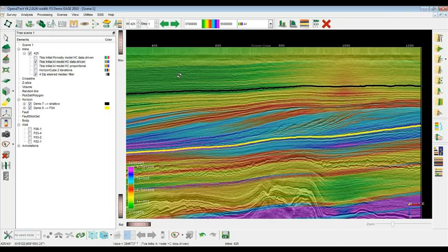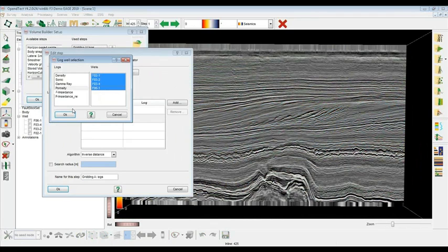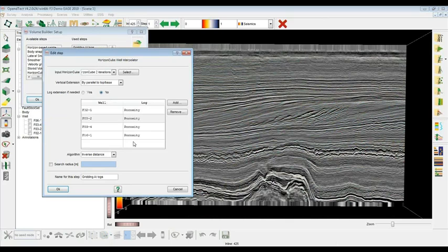And actually what has been done for impedance can be repeated for each and every log. So instead of specifying an impedance log, we can remove all this and add again a porosity log. It could be any quantity stored as a log on your OpendTect wells that is gridded back to a 3D volume.